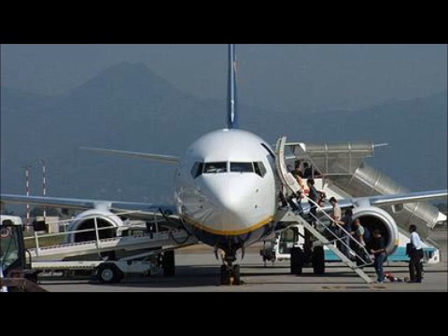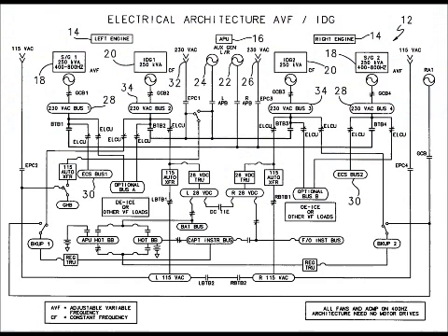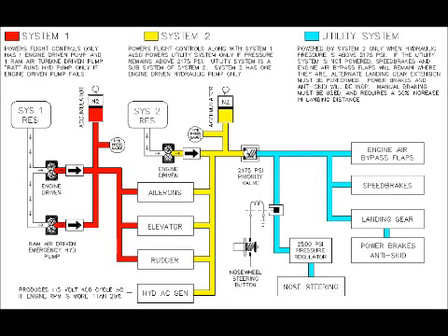APUs are also used to run accessories while the engines are shut down. This allows the cabin to be comfortable while the passengers are boarding before the aircraft's engines are started. Electrical power is used to run systems for pre-flight checks. Some APUs are also connected to a hydraulic pump, allowing crews to operate hydraulic equipment such as flight controls and flaps prior to engine start. This function can also be used on some aircraft as a backup in flight in case of any engine or hydraulic failure.